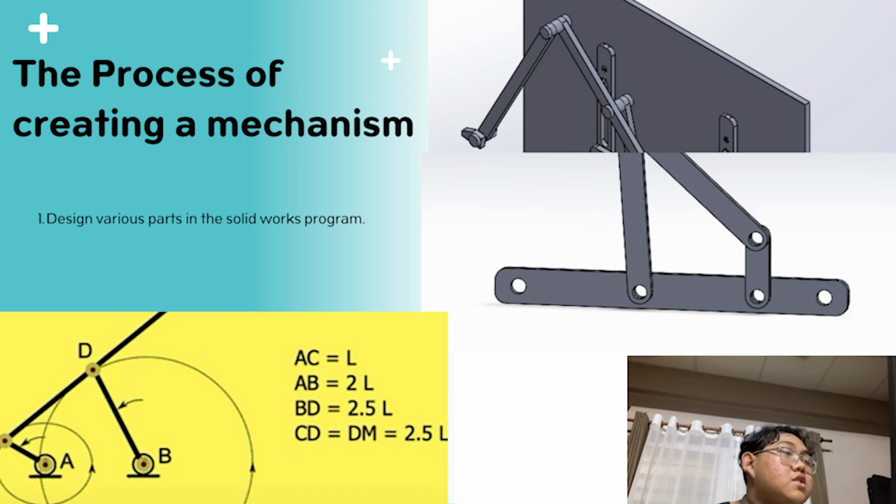We will use SolidWorks to design all 4 linkages and assemble the components. Next, we will simulate the movement of the assembly to see if it is consistent with the Chebyshev theory. Once we confirm the design theory, we will begin designing the pin for the link.